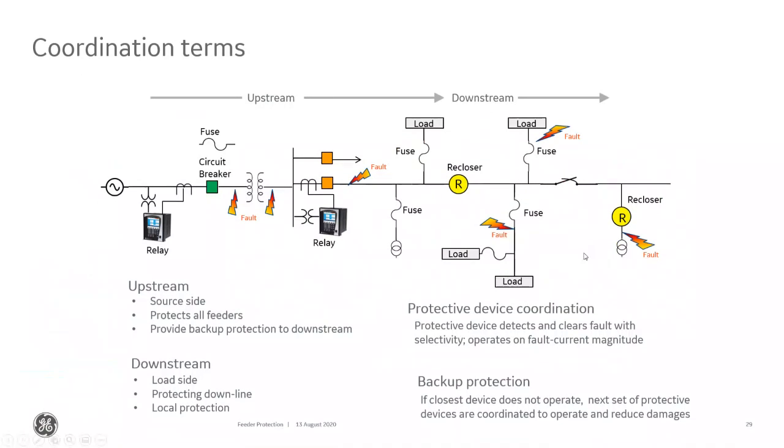there can be an issue, and this we ran into when I was working at Con Ed, where if you have a feeder, because it's Manhattan, Brooklyn, Queens, a portion of the feeder is always going to be underground. And we know underground faults are permanent in nature. There's no such thing as a temporary underground fault. It's usually the overhead. So usually the feeder comes out of the substation underground, then transitions to overhead to a pole top